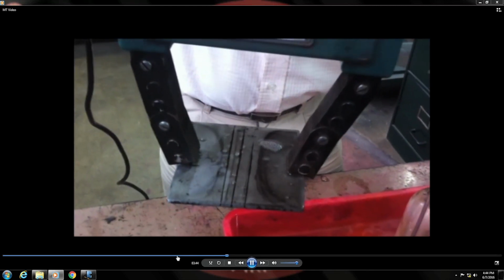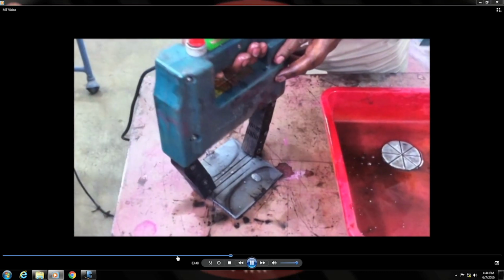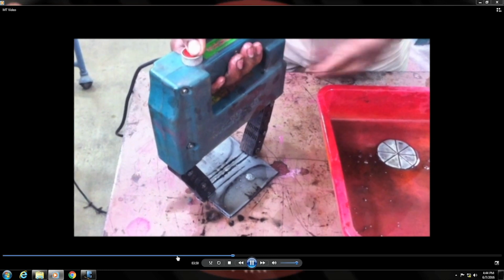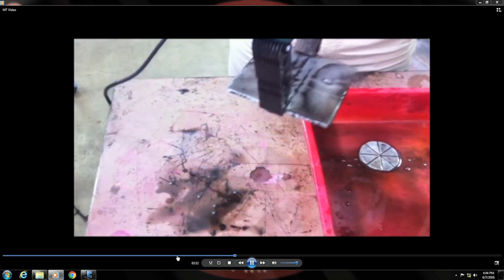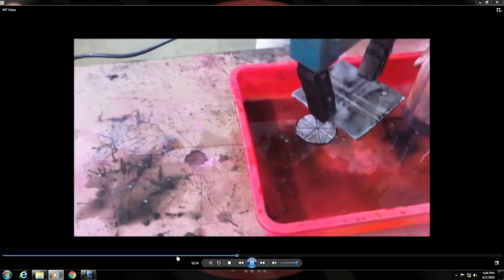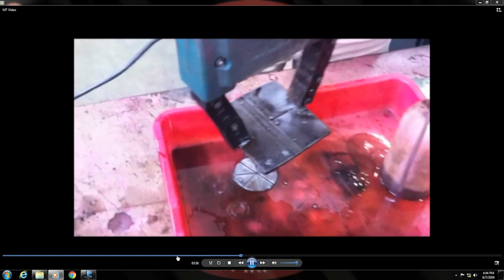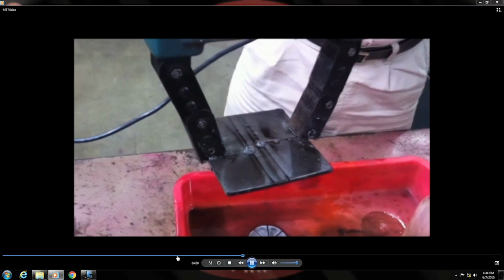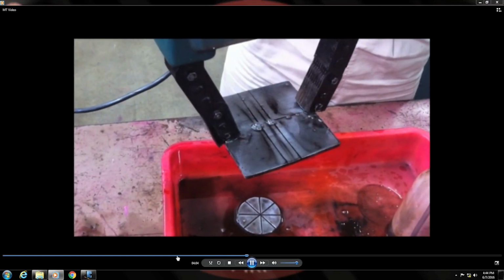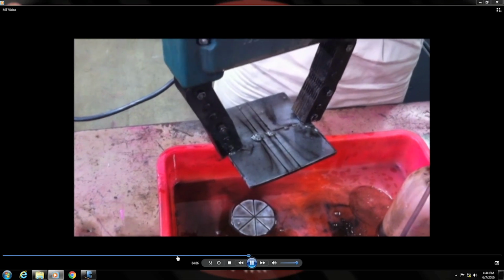Okay. And in this case you could see as I showed by that finger, that is the direction of the field, and most of the particles are going in a perpendicular direction. Okay, so, that is what indicates that the best visibility you have when the orientation of the flaw is perpendicular to the direction of the magnetic field.